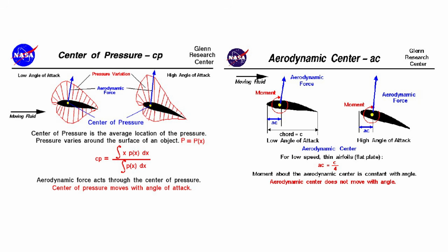Now, knowing the theory behind static stability, let's walk through how this applies to an aircraft specifically without a tail. Let's start first with longitudinal or pitching stability, considering a generic lifting airfoil with positive camber. In the reference frame of the wing, an airfoil will generate a normal and axial force, which can be translated to the wind reference frame with simple trig. The vector sum of the lift and drag vectors produced by the foil are denoted here by R.